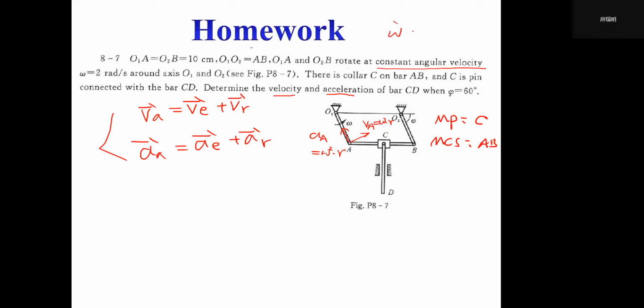So omega dot, the angular acceleration, equals 0. So this AA only has one component, that is the normal AN, because A tau should equal R alpha, and alpha equals 0, so this one is 0. And its normal component will be omega squared R squared over R, which equals omega squared R. So that's our hint for this example.